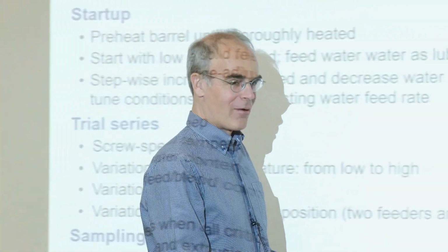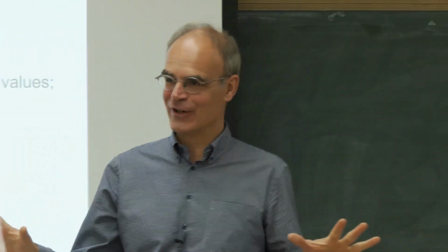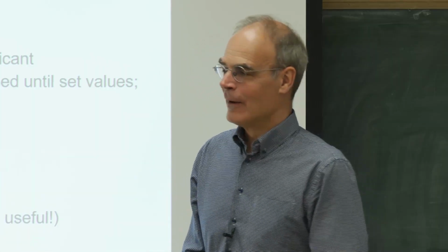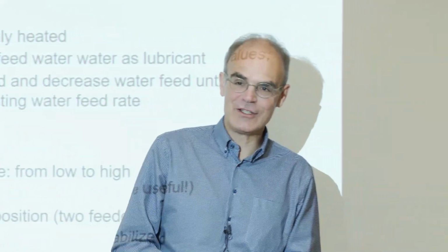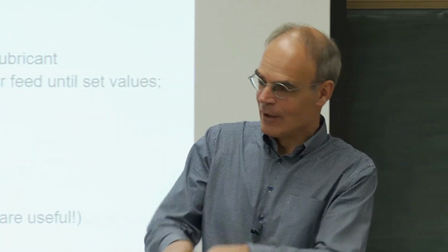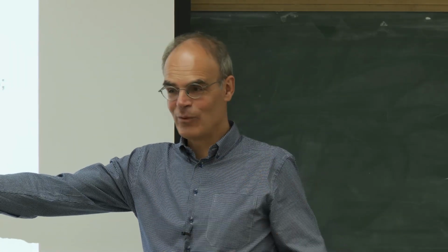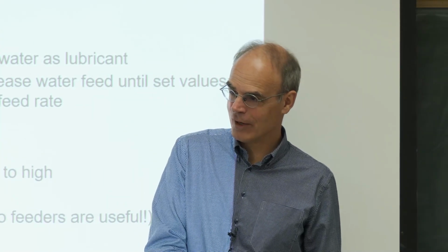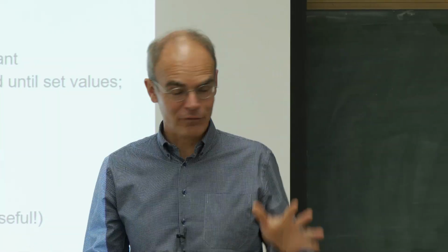It's way less work. Because one way you can shut down is just say, oh, I have my sample, there's some big red button, slam it, the whole thing freezes up. So you can just stop it, or you can just really go down. The thing is, then you have to dismount the barrel. We have a clamshell, so it's easy to get it out. But otherwise you have to pull out your screws if they're all that gluey, gooey stuff around. Then you have to scrub everything off. Not very appealing. Still happens sometimes if you have to shut down the trial because of unforeseen problems.